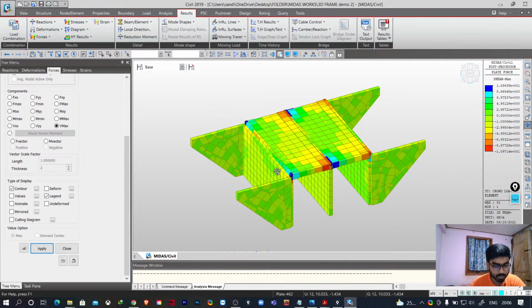Yeah, if you do not want horns, actually what it considers in case of this kind of structure, you can say culvert structures, we do have horns. Actually we need to provide the horns to reduce the shear in these corners, right? So if you do not want to provide horns, you just have to select these elements and change the section. You can always select these elements as I have showed you.